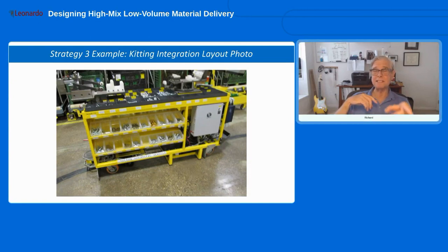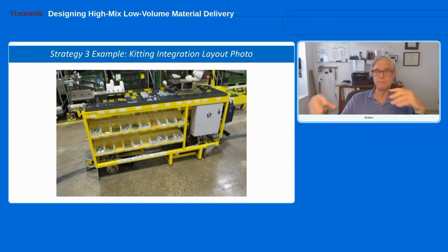They were doing this exact same thing, but much more simply. They had a kitting cell. They had AGVs, but the AGV was very simple. It didn't have any of the fancy stuff. The AGV was just moving the parts. And the AGV would come around to the line. The line I was looking at was the engine prep line for the Camrys. Right, so they're putting about 40 different components on the engine block.